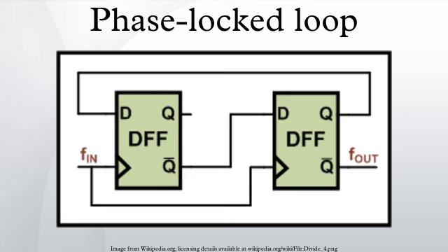Analog phase lock loops are generally built with an analog phase detector, low-pass filter and VCO placed in a negative feedback configuration. A digital phase lock loop uses a digital phase detector. It may also have a divider in the feedback path or in the reference path, or both, in order to make the PLL's output signal frequency a rational multiple of the reference frequency. A non-integer multiple of the reference frequency can also be created by replacing the simple divide by n counter in the feedback path with a programmable pulse swallowing counter. This technique is usually referred to as a fractional-n synthesizer or fractional-n PLL.